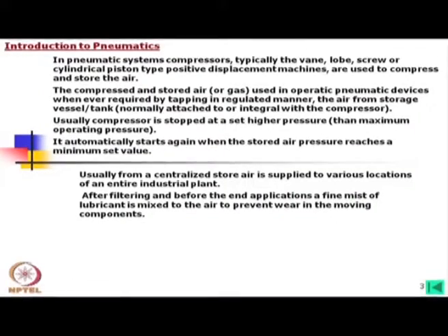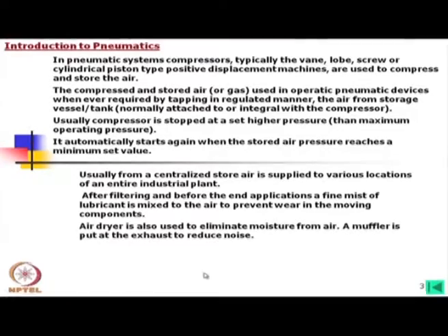In case of air, ordinary lubricant can be mixed, but before that your air should be dust free and dry. That means no moisture is allowed within this air. So after filtration or such preparations, you have to mix in oil; that is important. This is required to lubricate the moving components.